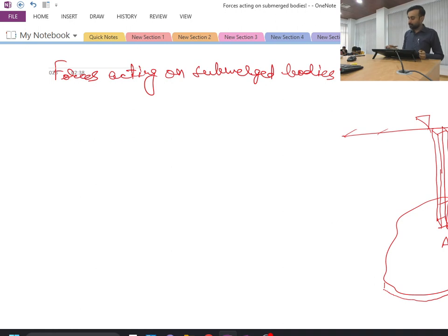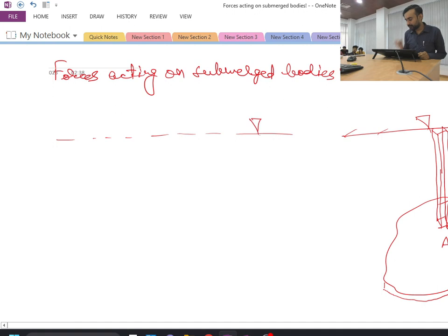For this object, I have tried to give you the three-dimensional representation. Now I will try to draw it on some orthographic projection plane, and there I will try to see how it looks. Let me draw over here: this is nothing but the free surface. From this free surface, if I see this particular planar object from the side view, then I will be finding it as nothing but a strip of constant thickness. Is this one clear?